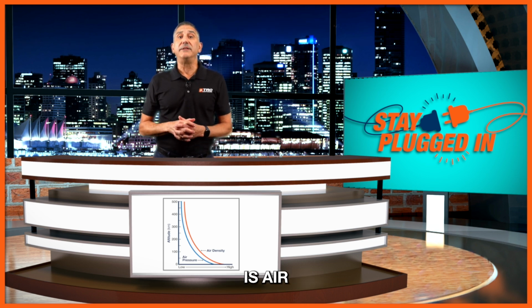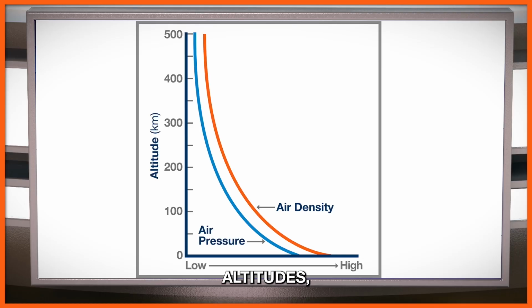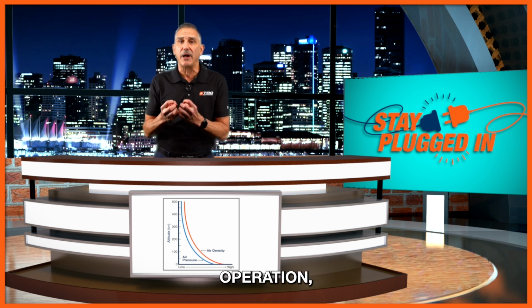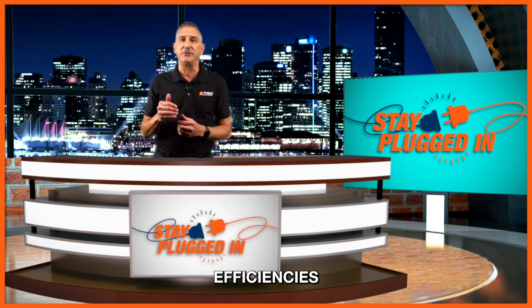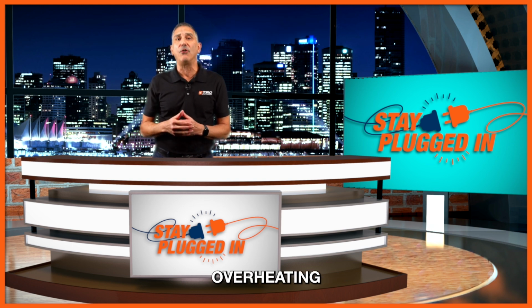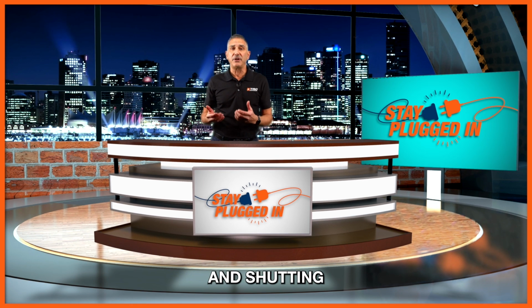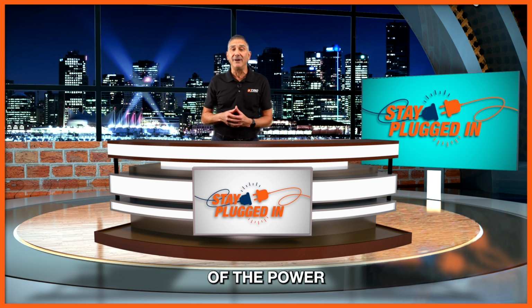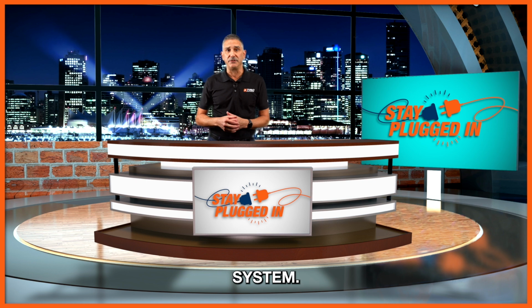The first one is air density. At higher altitudes, the air is thinner and less dense, which means that the ability to use air to conduct heat away from the power supply is less effective. Since power supplies generate heat internally during operation, reduced cooling efficiencies can cause higher temperatures, potentially leading to overheating protection and shutting down, along with the reduced reliability or lifespan of the power supply, and in turn, the overall system.